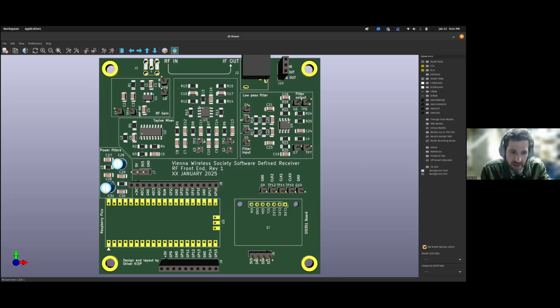Every pin is labeled, so you know this particular pin on the PCB has this function, particularly for all the breakout pins, and you aren't having to find the data sheet or have a printout of the data sheet to remember what each pin is. So you will thank yourself in the future if you put a lot of silkscreen art on your PCB, put your notes on the PCB, and make it as self-documenting as possible. So that's what I've tried to do here.